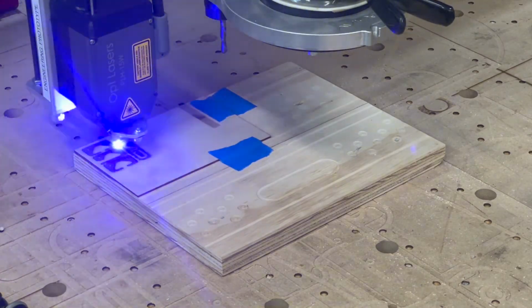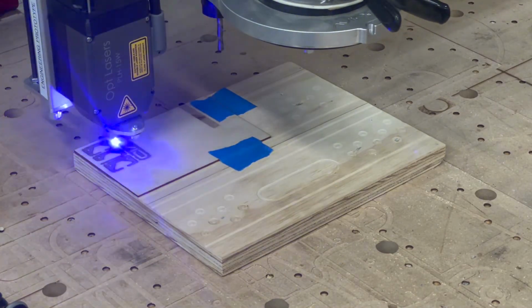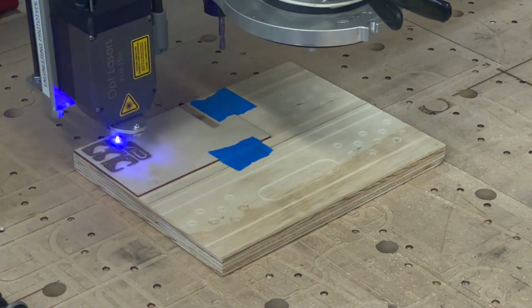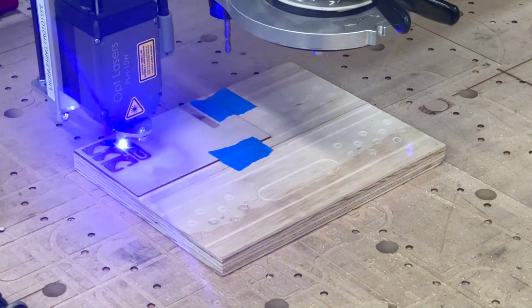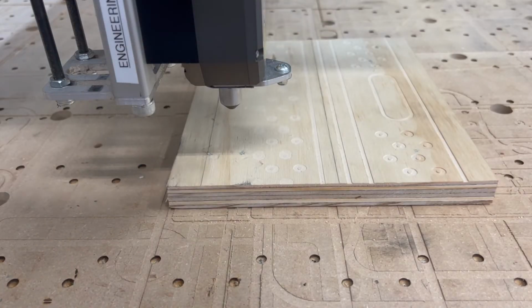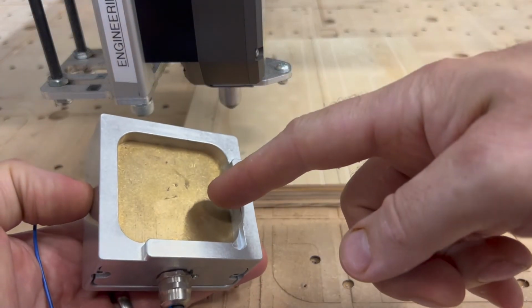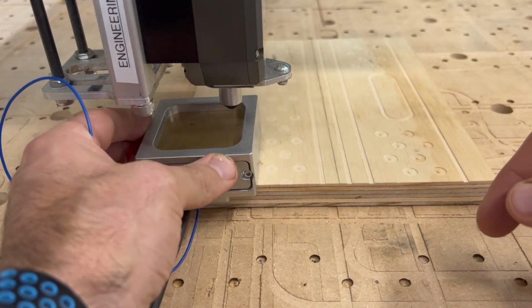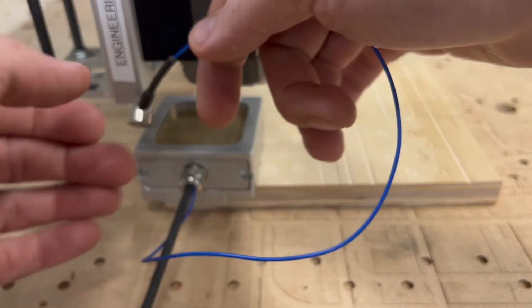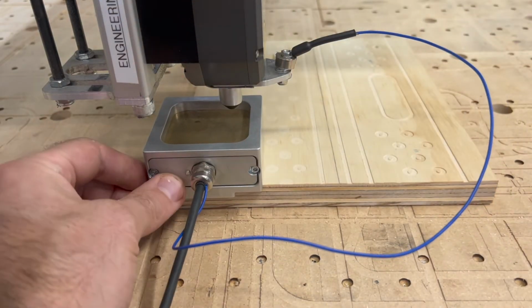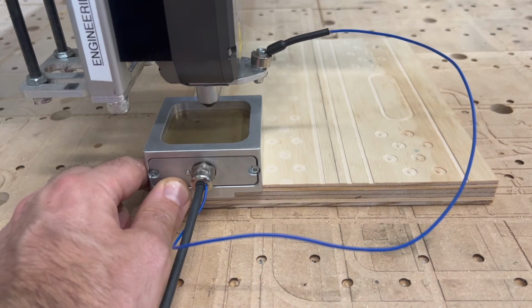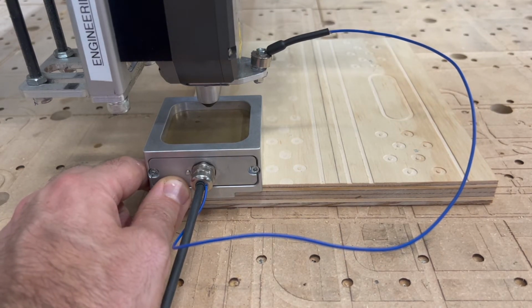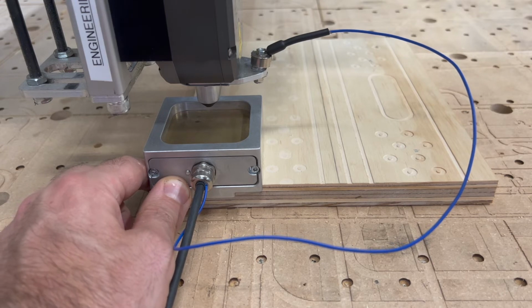And to set this job up, we're going to be using the touch plate to find the corner of that raised section of plywood, and then again using the touch plate to find the top of the material that we intend to laser on. We'll start out by taking our 0 plate and hanging it off the lower left-hand corner of this sacrificial piece that I have attached to my spoil board. You'll take the magnet that you would normally put on your spindle bit and actually attach it to the bolt on the mag plate. Jog the laser nozzle over the top of the touch plate, and then once you have that set up, we're going to open the touch plate utility.